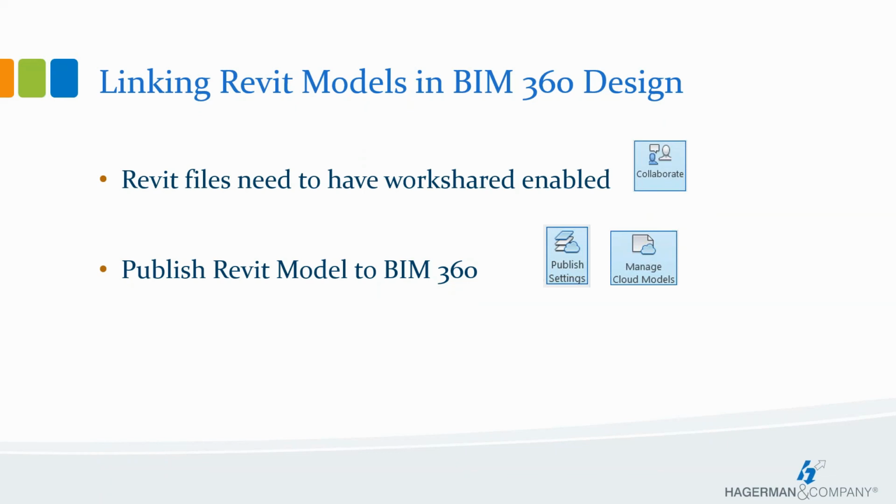Initially, when you enable work sharing, it's going to publish a model to the cloud, and it is a duplicate at that point in time of the work shared model. However, it does not have work sharing enabled. As soon as you save the Revit file again and save to Central, those files will no longer be the same. That published model is primarily used for the non-Revit users who don't need to see all the changes throughout the process of the design.